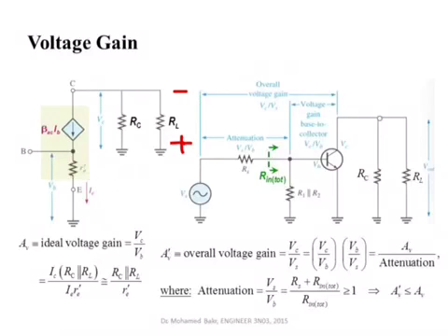So if you want to calculate the ideal voltage gain, which is the ratio between the collector voltage and the base voltage, not the collector voltage to the source voltage. Source voltage is not shown here. I'm going to get to that in the second figure. But this is what we call the ideal voltage gain, VC over VB. We agreed that the collector voltage is what we're measuring, and here we should have a negative sign taken into account. I'm getting the value between this voltage here, plus and minus with this polarity, and V base.